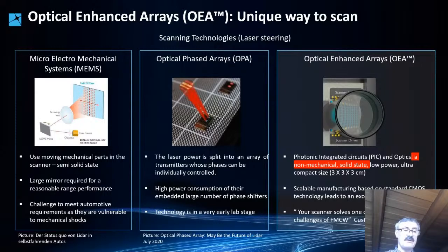The probe beam is created by the source numerical aperture and focal distance of the collimator. The beam direction is defined by the location of the source on the Fourier plane of the collimator. The OEA consists of a photonic chip having switchable output apertures, what we call sources, and a collimator having the photonic integrated circuit with those sources in its Fourier plane.